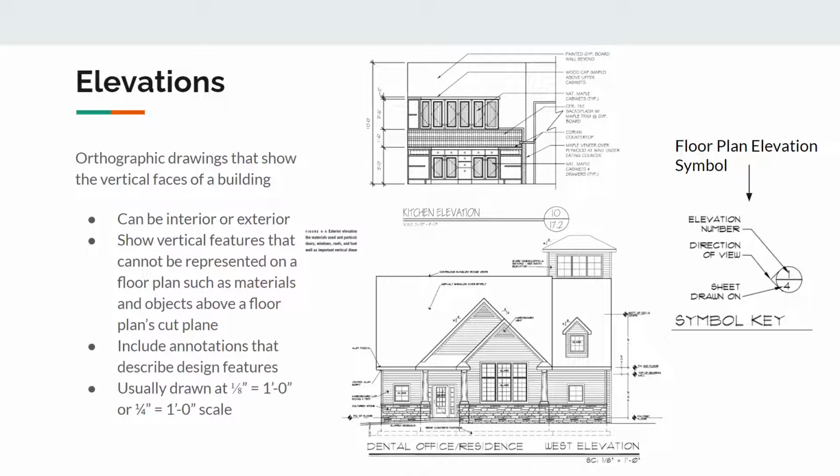But pretty much all of these different drawings that we're creating, you're only going to be providing the bare information that is necessary, essentially, because you only have a finite amount of space, and you don't want your drawings to get too cluttered up. So we're not going to be putting a bunch of dimensions that are redundant or unnecessary. We're only going to be putting what is required in order for somebody to build it, so that we can maximize our sheet real estate when it comes to putting in annotations and dimensions.